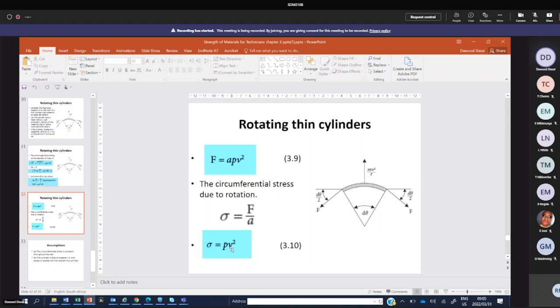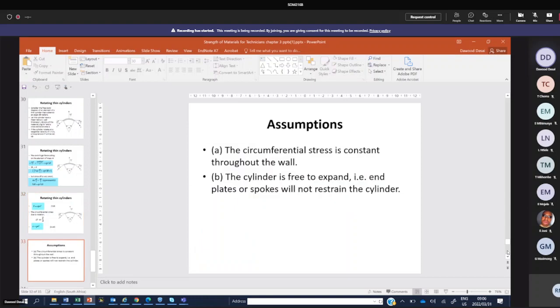So if you got a case now where you got a thin cylinder under pressure, you use your normal formulas I already taught you. And if they tell you in the question it is rotating, so you say plus rho V square. So you add that up. So the total stress will be your circumferential stress according to the formula I gave you already, plus rho V square. You're going to add the rotating component also. If the cylinder is not rotating, then you ignore all this. It's only one simple formula. You've got two stress parts now. One due to the internal pressure and one due to rotation. This is the one due to rotation. So read the question carefully, see what's involved, and then you answer.